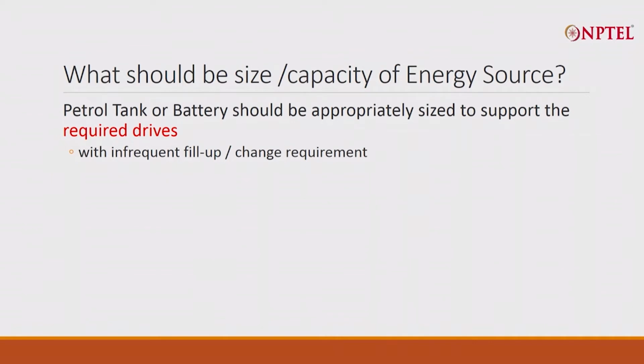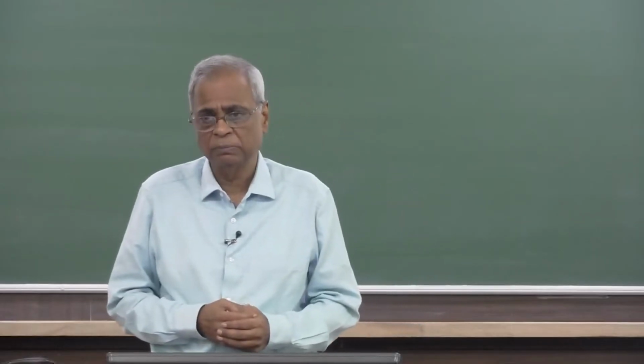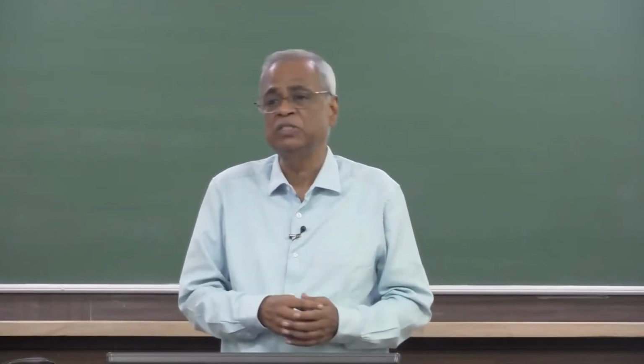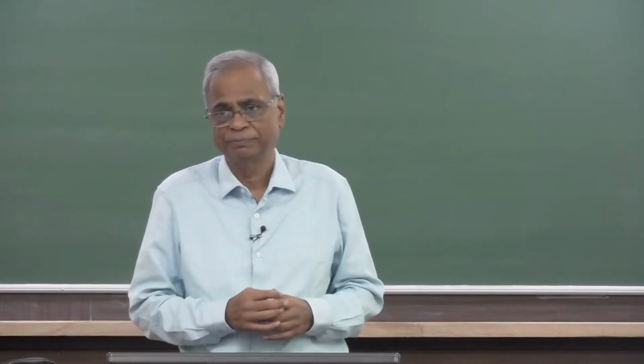So my petrol tank should be so large that I should be able to drive 250 kilometers, or my battery should be so large that I have enough electricity to drive 250 kilometers. So it will depend on the required drive, that is a user requirement, and from the user requirement you decide what is the petrol tank size or battery size. Otherwise it will require frequent fill up or frequent charge, which generally you do not like.